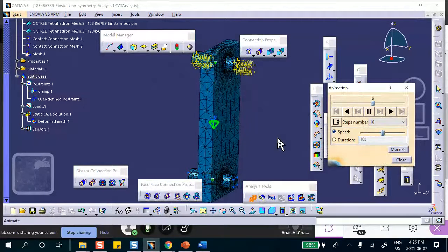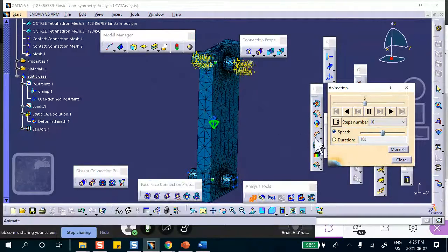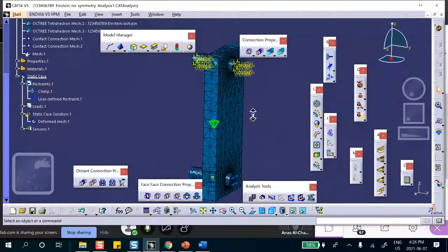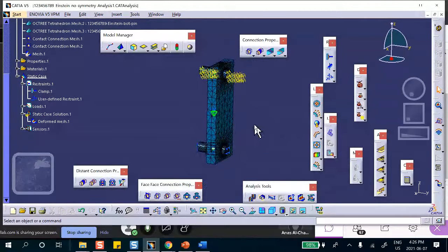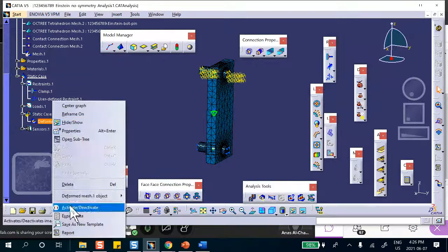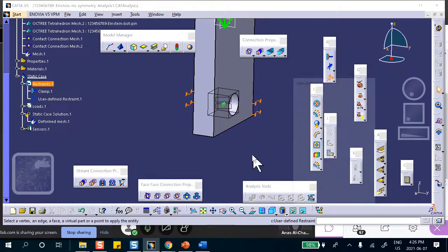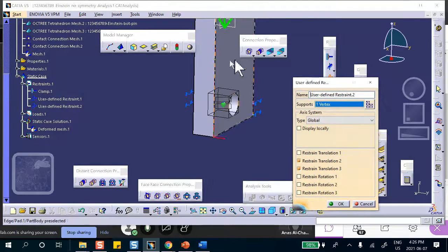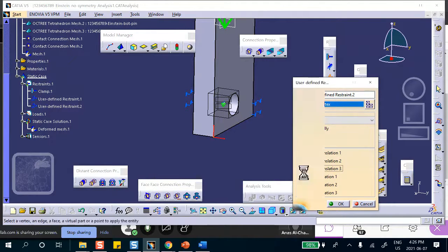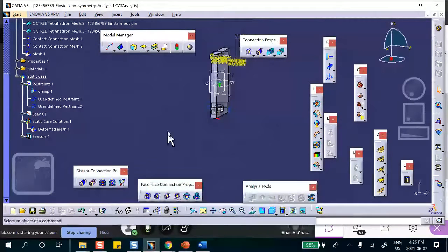Oh, it's the block that's moving. That guy doesn't come out. And you can visualize that if this was an ideal world without any friction, the block can move. So deactivate that. Just fix one point of the block, one corner point. It doesn't matter which one you put, and just don't move in the direction Y, right? Direction Y. That will take away the rigid body motion.